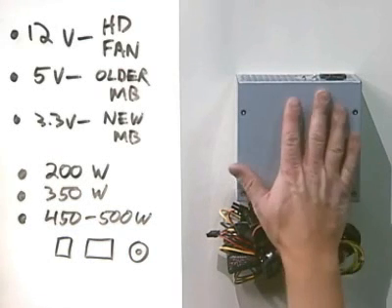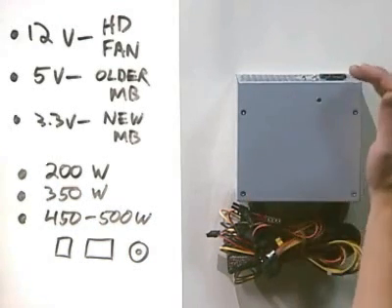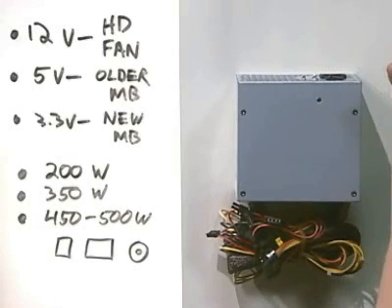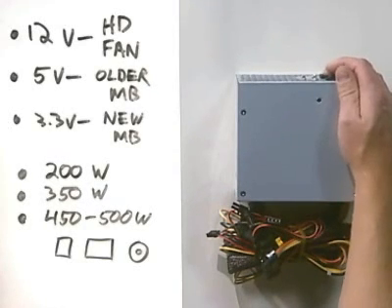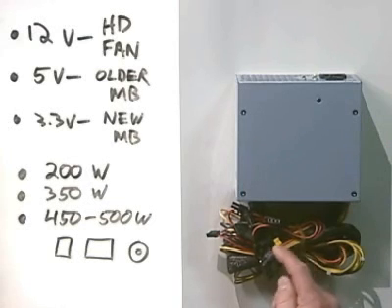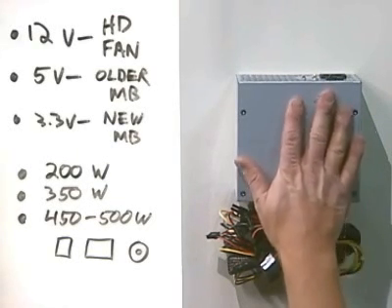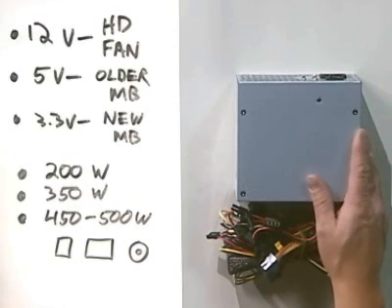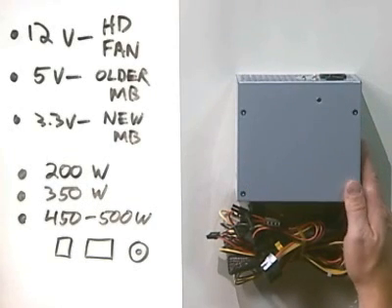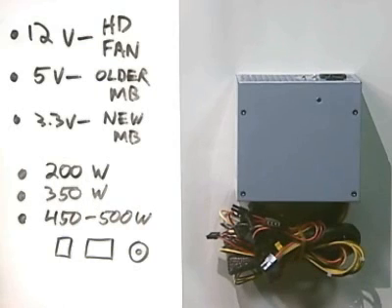Obviously, if you're plugged into the wall outlet and there's a problem with the AC side of the power, for instance, if you have a brownout or a blackout, obviously you'll lose power again on the power good wire and the system will go down. If the power supply is being overstressed because we have too many components on it drawing power from it, that will also cause the power to be lost on the power good wire and cause the system to shut off.